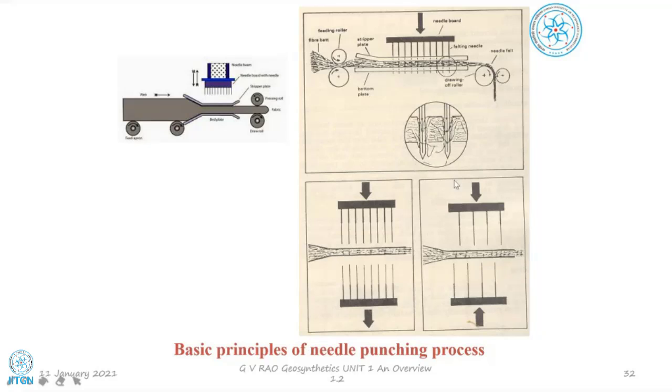Okay. So what was happening now? The fibers which were horizontal earlier were actually becoming vertical now. So that is where the punching is going to help in bonding. The mechanical bonding is happening because of this system. Okay, as I will repeat, it all depends upon the kind of needle, the spacing of that, and whether you are punching from both directions or not now. Many things are there. There are 7 parameters which are going to matter. So our student actually long ago produced so many varieties.